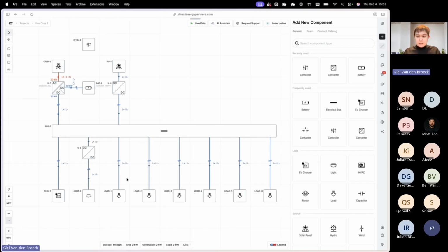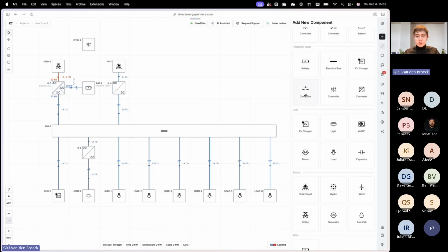And then we also had digital I/O originating from that controller, because we built in pre-charge on every load branch over here. Here we added pre-charge contactors on all the load branches, because all of you who are familiar with DC systems know that when you energize a branch that's at 0 volt initially, you have to charge all the input capacitors of these components at once.